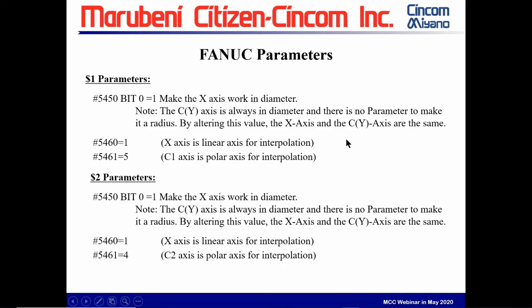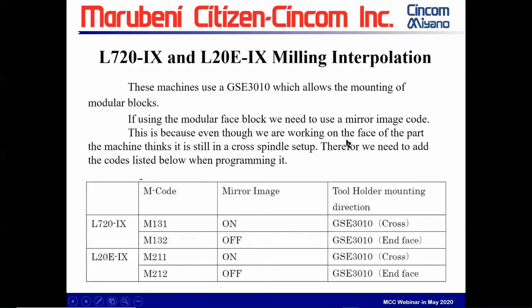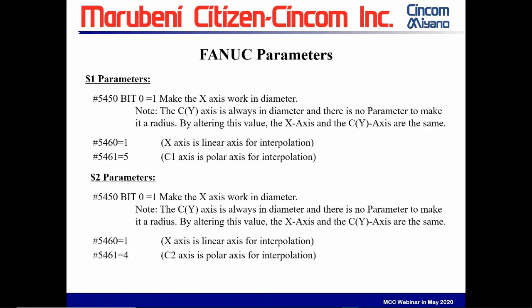That never really changes. I got a question here for you, Ron. Sure. Can the G12.1 be programmed in diameter and radial values? No. G12.1 is always in direct distances. In other words, if you're making a 250 square, you would be programming up 125 and down 125. So you would have to say that is diametric. It is not cut in half.